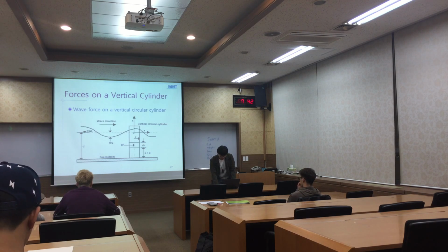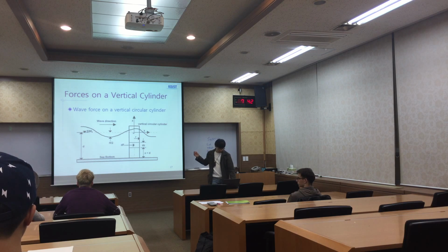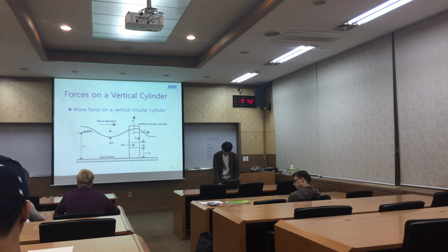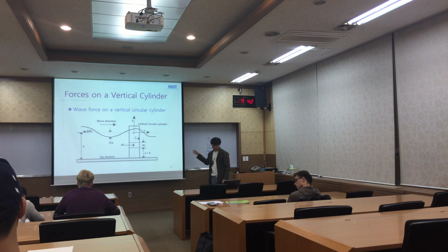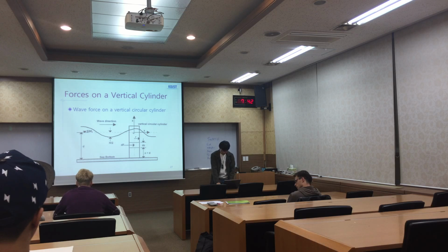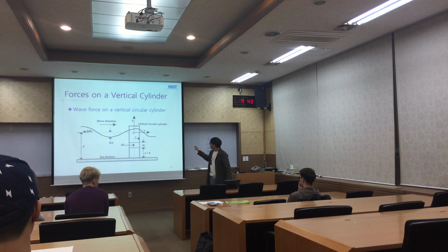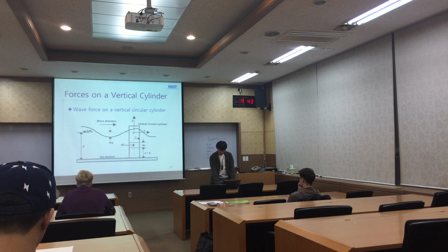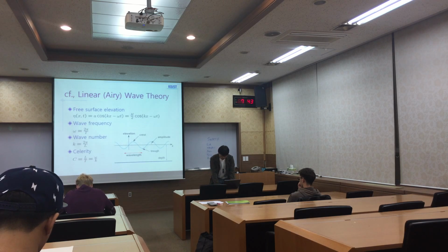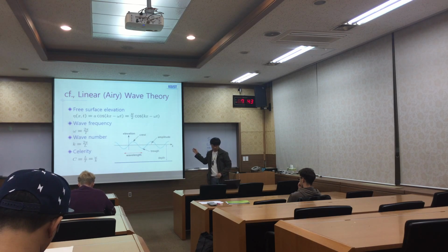You can see this picture. When you think about the pipes underwater, we should consider the forces on pipes, and there are forces caused by waves, and we should consider the horizontal force and vertical forces and control them to be balanced. And so we'll check the wave theory to use this idea.